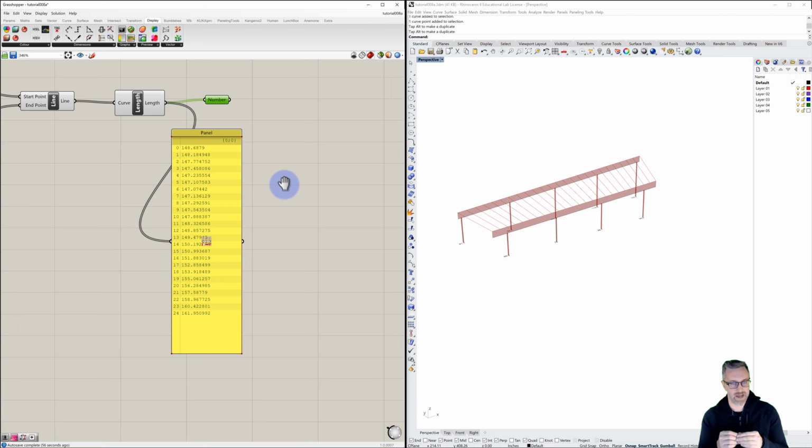is, so the maximum, and these are from a really simple span table. This is the disclaimer: this is not a structural design project, but one that deals more with logic. That being said, from an old span table that I saw, the maximum span for a 2x12 was 225 inches. So what I want to start with is that any value greater than 225 inches, I want to change so that I know it's not within the appropriate depth.